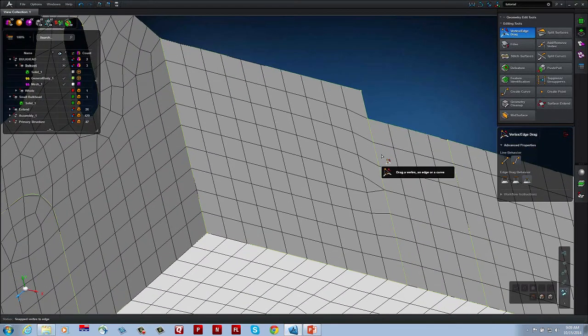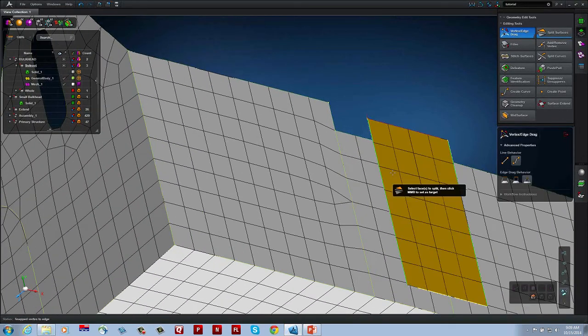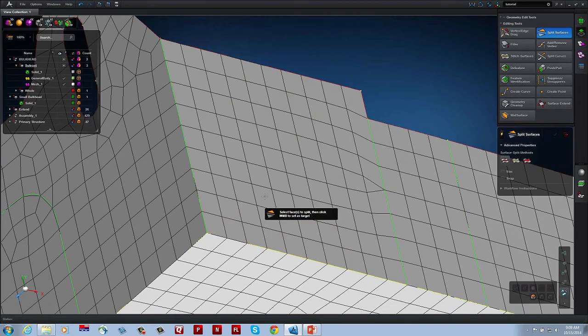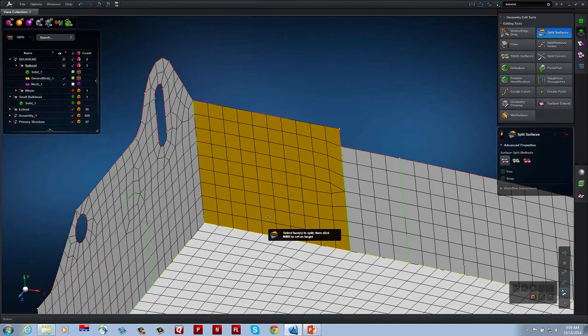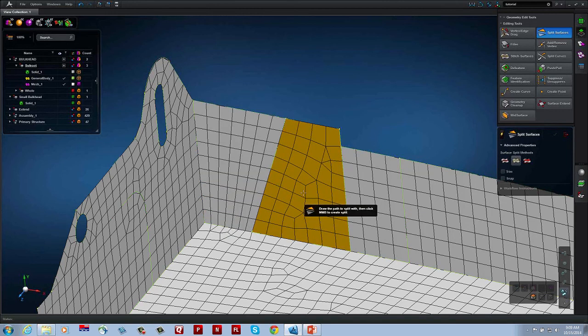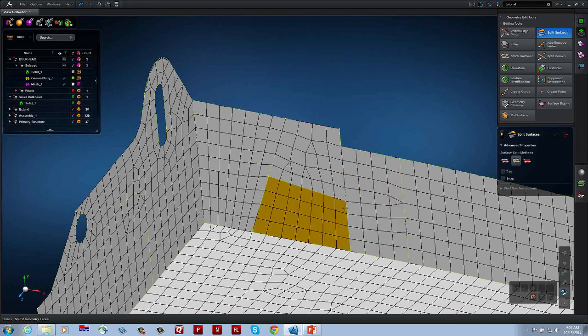I know a lot of times people spend a lot of time trying to get the mesh they want, especially in the area of interest. So I'm actually going to come in here. Maybe I want to automatically refine the mesh in this area, and I'm going to do that by introducing some splits. Because if I introduce some splits, I can go in and use different mesh characteristics in different areas of the part. So once again, as I introduce the splits, the mesh automatically updates, automatically congruent.